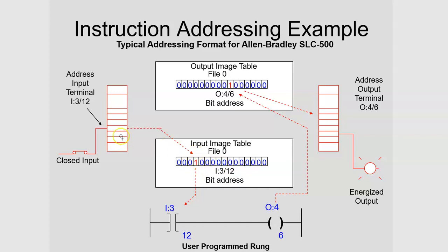And because this is closed, in memory there'll be a 1. This will update to, if it was a 1, it'll stay a 1. If it was a 0, it'll change to a 1. So this switch right here, being open or closed, affects what's in this register, a 1 or a 0. A 1 if the switch is closed, a 0 if it's open.